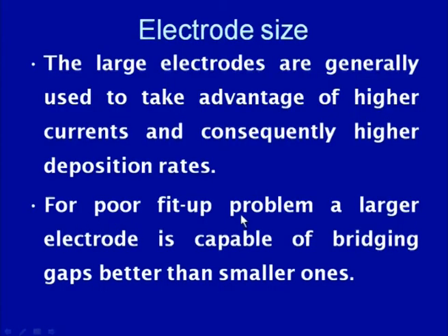For poor fit up conditions, large diameter electrodes also help in bridging the gap in a better way than the small electrodes.